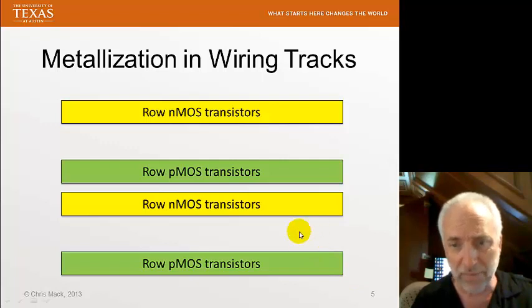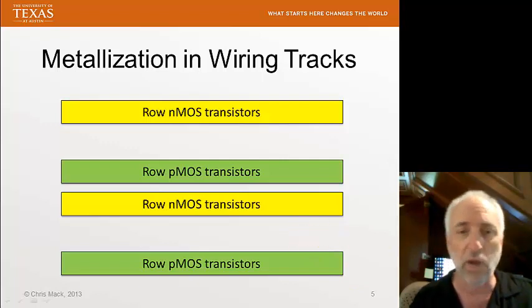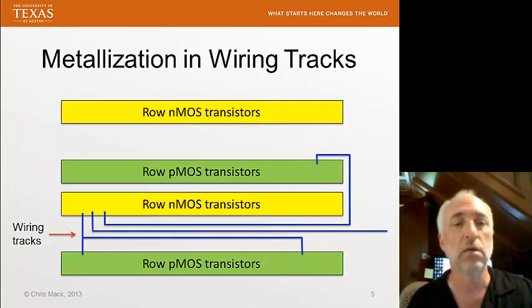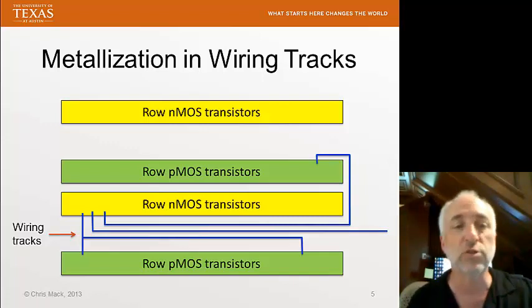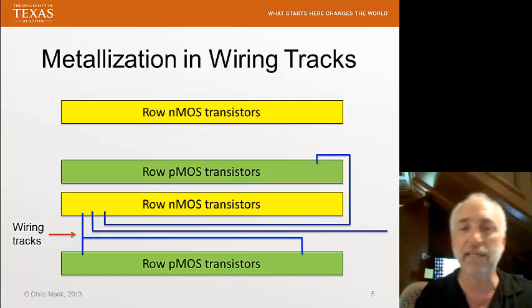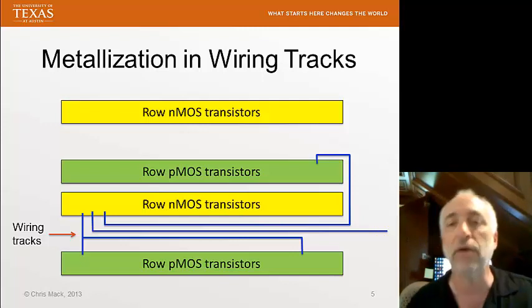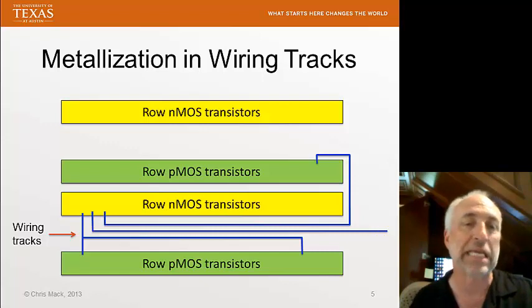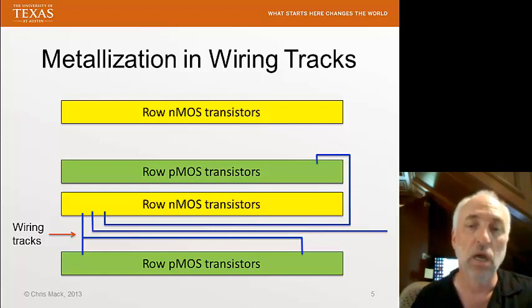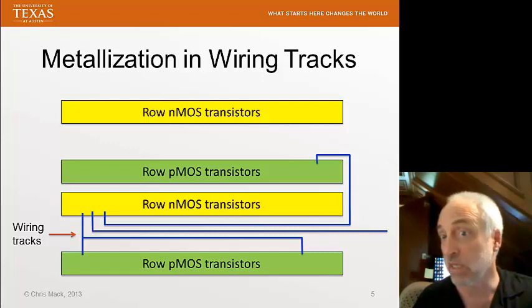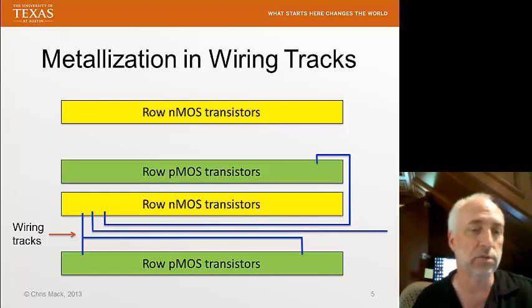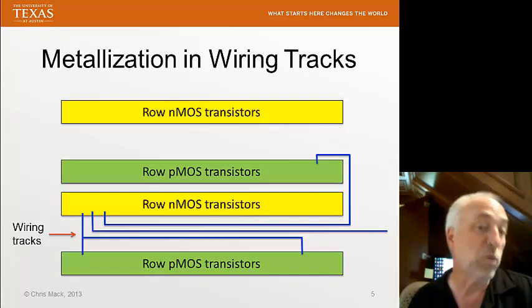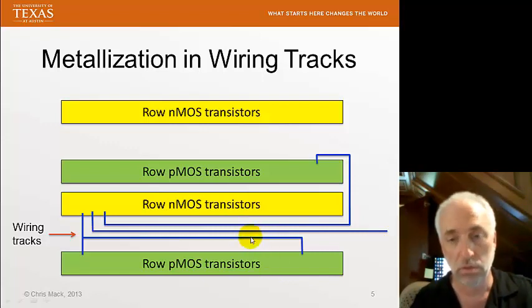The space in between where we're going to run our wires to make our connections, we call these runs of wires tracks. So a track is a space where I'm allowed to run a wire to make a connection. The more wires that I need to run and the more connections I need to make between transistors, the more width I have to allow to run these tracks.